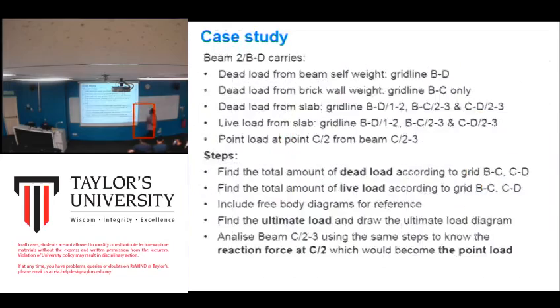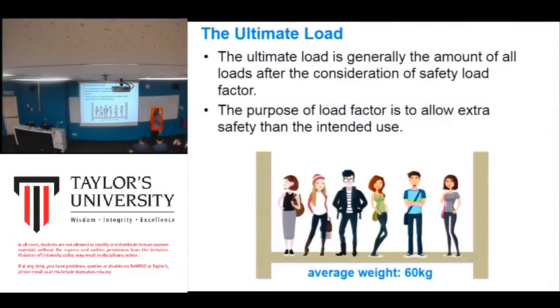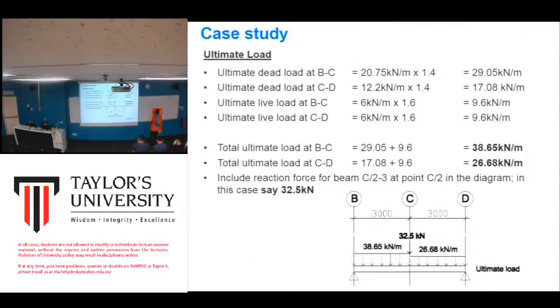Is it easy? Very simple, right? This one is the UDL. And after you have managed to get this UDL, you can find the reactions at B and also at D. Because later we want to know the shear force and the bending moment of this beam, the value of it.